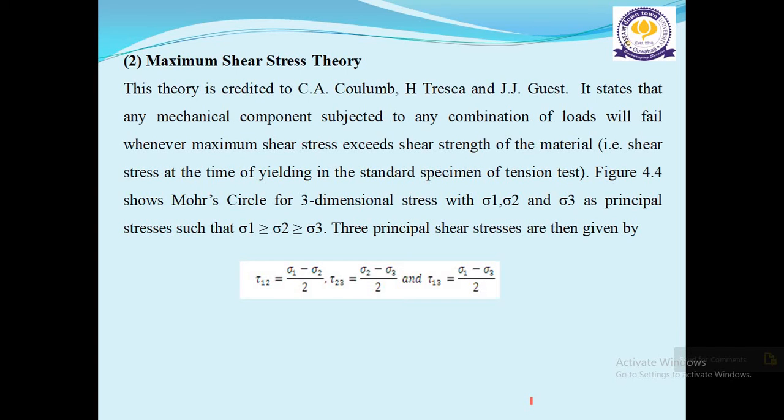This theory states that any mechanical component subjected to any combination of loads will fail whenever maximum shear stress exceeds the shear strength of the material, that is the shear stress at the time of yielding in the standard specimen of the tension test. I will show the figure in the next slide, where